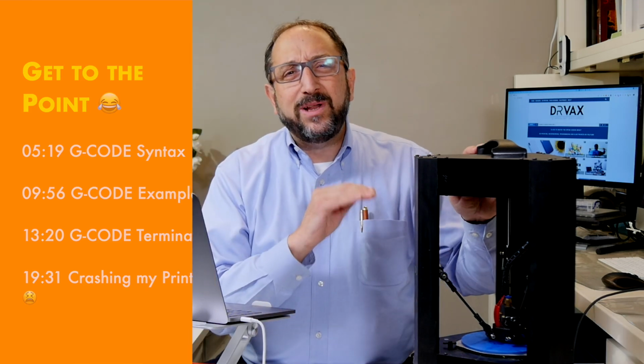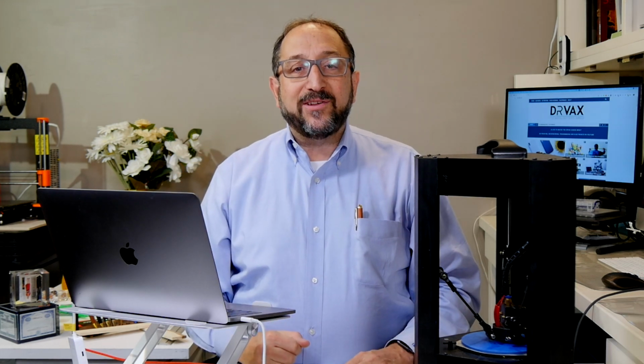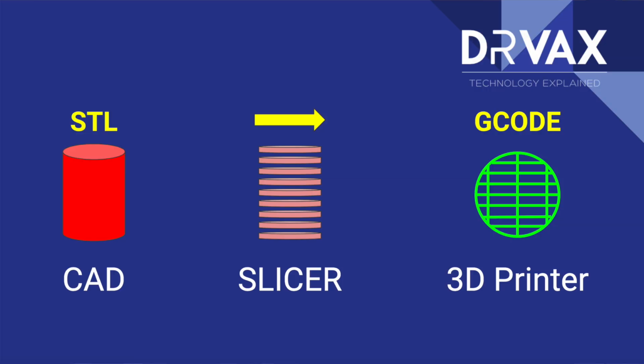3D printers can't actually print three-dimensional objects. 3D printers are really very simple machines. They print a layer at a time. It's almost like printing on a piece of paper and then putting a new piece of paper in and printing another layer. Except they stack those pieces of paper, those layers, one on top of the other to create a three-dimensional object. So you need to take your three-dimensional shape and you need to convert it into a series of layers. That function is done by a slicer, and the format used by many FDM-style 3D printers, filament-based 3D printers,